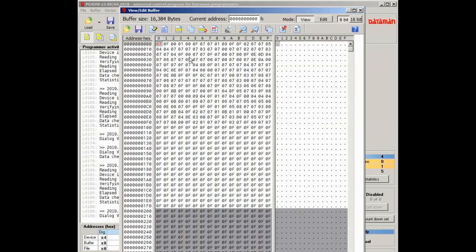There's no weird kind of patterns or anything that you normally get when ROMs fail. So that's quite a surprise. I need to go back now to the board and see if we're still getting the same effect, and possibly what's pulling those lines high.